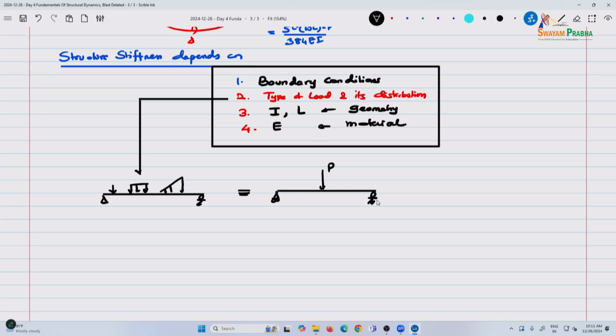It's better to get into a point load. You can try what the stiffnesses are coming from both cases, and that's a good exercise for you to try. Put an equivalent, convert it to a point load and see if the K values are different. But since we have a spring stiffness model, you get an equivalent load that creates the same moments and shears.